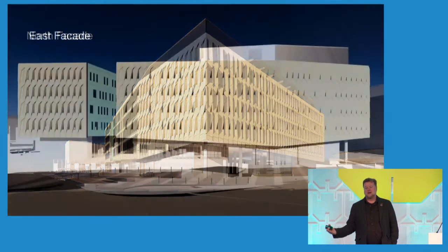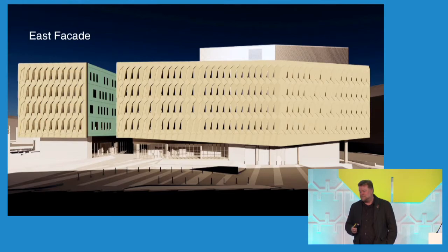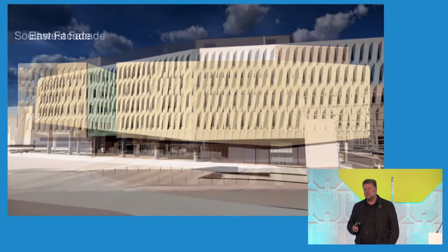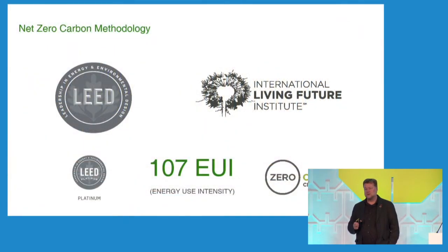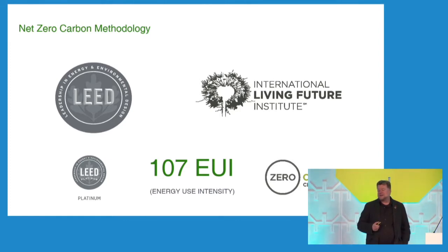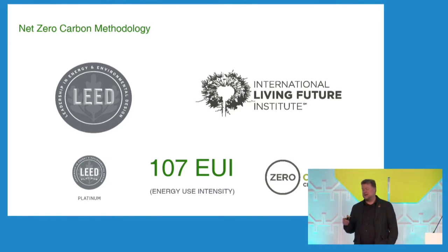So of course it meets LEED Platinum, but for the net zero carbon, what we've decided to do is to work with the International Living Future Institute, and those are the standards that we're working to for accreditation of our buildings. And the other important thing is the energy use intensity. So you see here we've achieved 107. To put that in perspective, most high-end performing laboratories would be around 4 times that, around 400, and a very efficient one would be 300. So the other side of the equation is creating incredibly efficient, high-performance solutions.